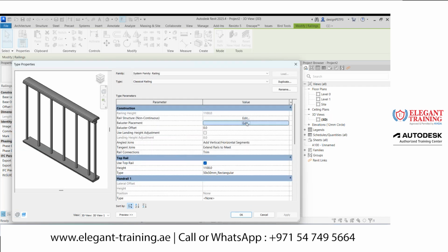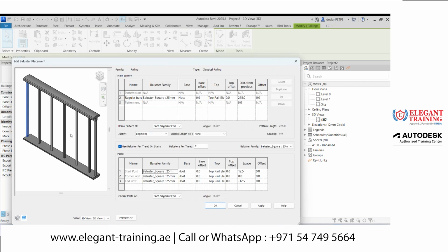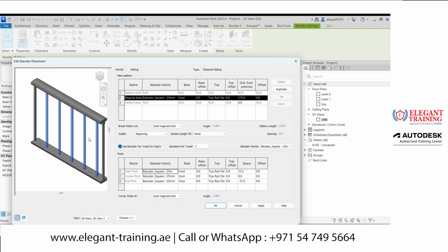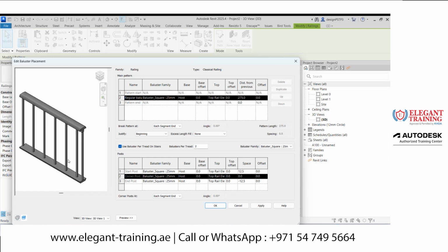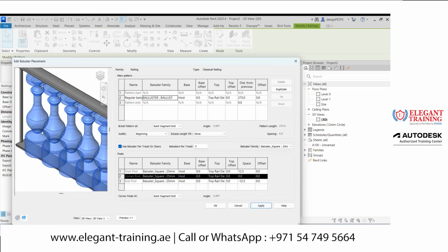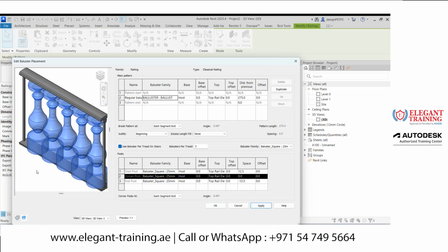I click edit. Okay, now in the baluster placement, you can see this is the regular balusters. You can see it in the center one, and this will be the start post. Okay, and this will be the end post, and the corner post is not visible right here because only a piece of railing is given here. So let me change the regular baluster family to the baluster we created. This is the family we had added. Click apply. Now you can see our balusters are placed over here.